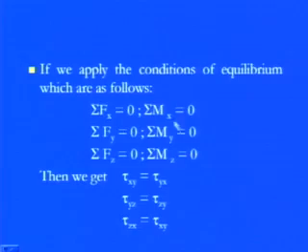It means that the summation of all forces, the internal forces coming out of that, or the external forces if they are applied, the summation of all the forces in x direction, y direction, and the z direction, they are 0. Or we can say, if we take a point like Q, if we have pivoted this point Q, and we take the moment about this point, like summation of these Mx or My or this Mz, that means if you are taking the moment about the x, y, or z axis, and you sum up those, if it is 0, we can say that it is well under equilibrium conditions. So for that,